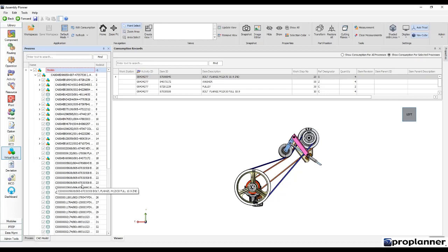Clicking on the CAD model tab at the lower left will display a tree of CAD nodes as defined inside of the CAD model. The user can interact directly with the model tree. They can select a node. They can turn on and off its visibility via a checkbox. Many different functions are available that are common by right-clicking on the selected CAD node or nodes, as the tree does support multi-selection. For instance, we can zoom to a particular node, isolate a node, isolate the selection, and also show and hide the parts as specified.